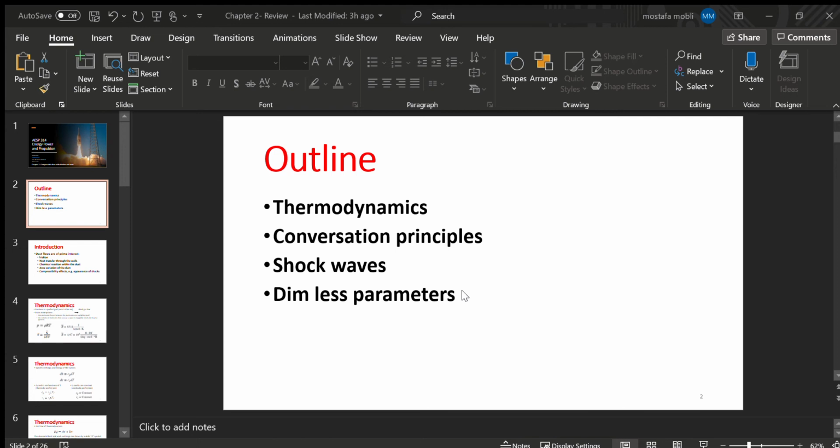So using those, you can come up with these equations for the pressure ratio between the two states. P2 over P1 is equal to T2 over T1 to the power Cp over R, which is equal to, we know that Cp over R is gamma over gamma minus 1, so T2 over T1 to the power gamma over gamma minus 1. And you can actually use the ideal gas law to rewrite this equation and come up with the relationship between pressure ratio and the density ratios. P2 over P1 is equal to rho 2 over rho 1 to the power of gamma. Any questions?